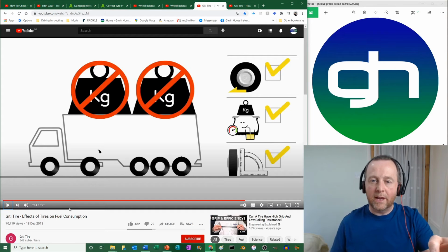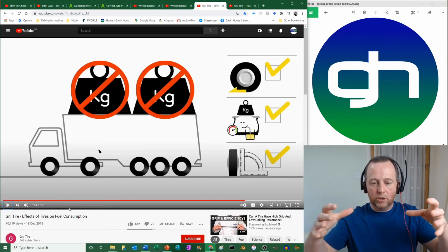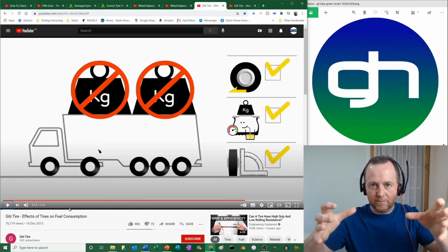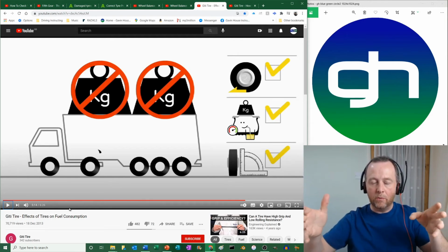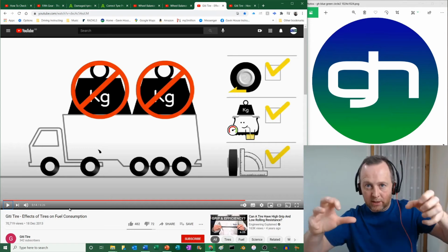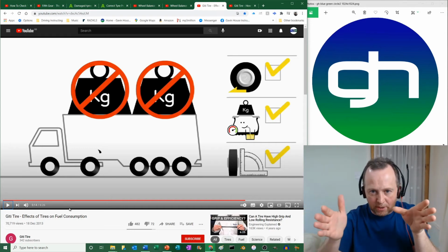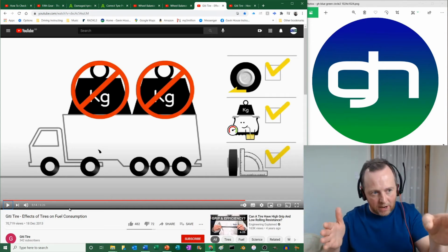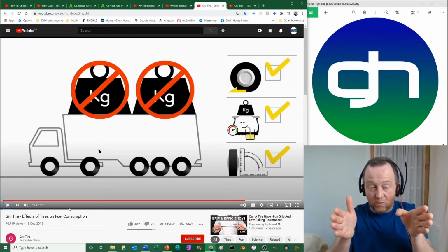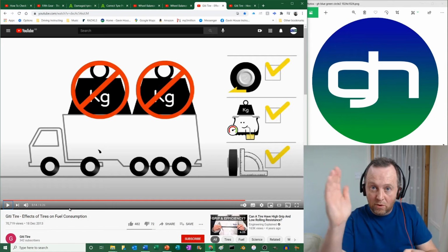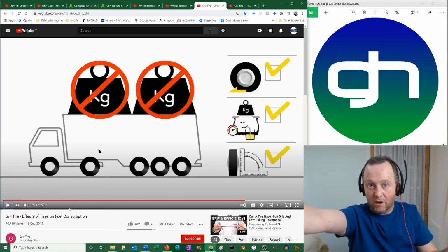So wheel alignment, that they're saying there, that's when the geometry of the car, when you hit lumps and bumps, there's lots of bolts and arms that connect the wheels onto the car. And when you hit a lump or bump, sometimes it gets a jolt and something loosens and something goes slightly out. Now, if your wheel alignment is wrong and it's slightly off, like it said 1%, it's going to move you to the right, for argument's sake, over a kilometre.